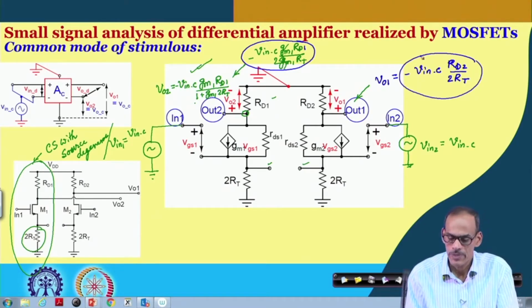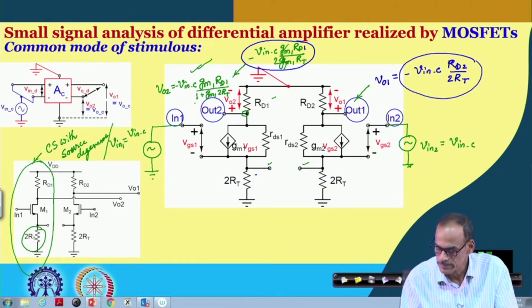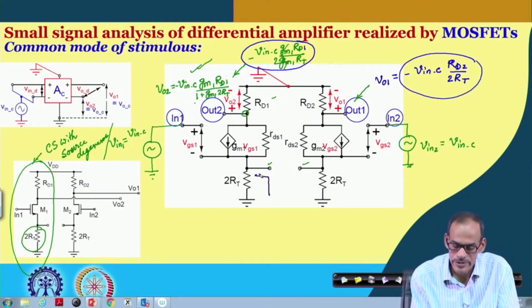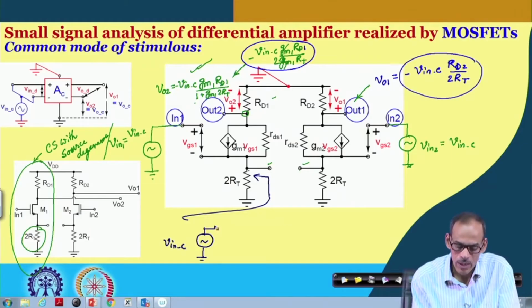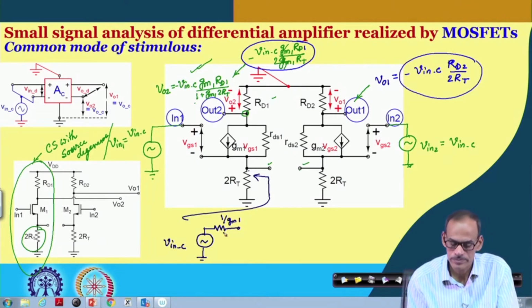Now, if I consider on the other hand the signal at the emitter, it is similar to our previous discussion. Before we connect the resistor, these two resistors, we have signal coming here very close to the applied input voltage, which is V in C, and then a Thevenin equivalent resistance of approximately 1 by gm1.